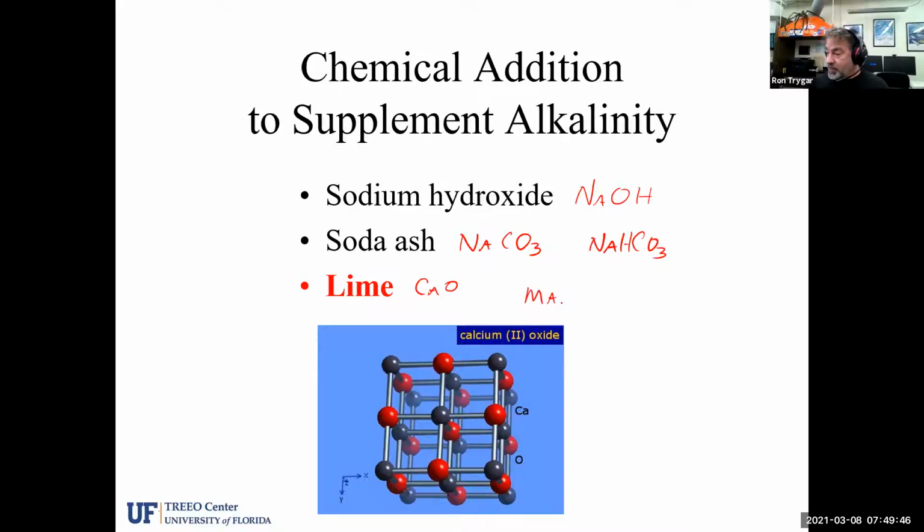I'm going to write this up on the slide here. Magnesium is another one that's used. Magnesium hydroxide can be utilized. That's another good chemical, sometimes used for odor control in the collection system. And ammonium hydroxide is also available. We don't really want to add more ammonia to this because then we're going to add more work for us as far as a treatment plant. So those are the more common chemicals to see us use in the treatment facility.